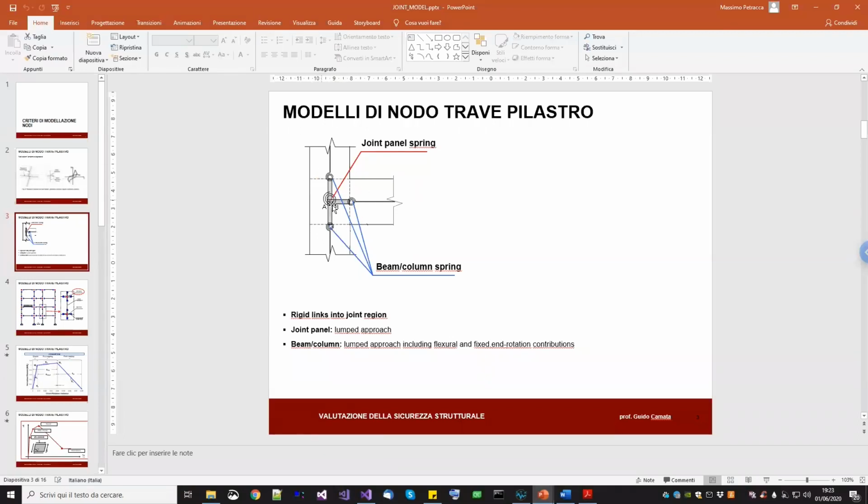And then you take this node in the middle, you duplicate it, and then you attach the column's joint offset to the original node, the beam joint offset to the secondary node, and then the first and secondary node are connected together using a zero length spring, basically, that is continuous in all the degrees of freedom except the two rotational degrees of freedom about X and Y.